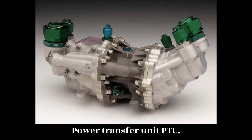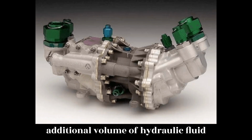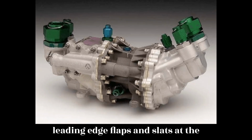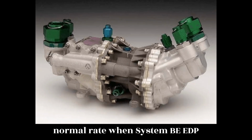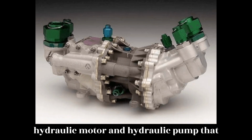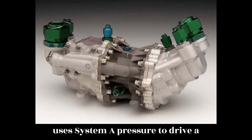Power Transfer Unit, PTU. The purpose of the PTU is to supply the additional volume of hydraulic fluid needed to operate the autoslats and leading edge flaps and slats at the normal rate when System B EDP malfunctions. The PTU unit consists of a hydraulic motor and hydraulic pump that are connected through a shaft. The PTU uses System A pressure to drive a hydraulic motor.